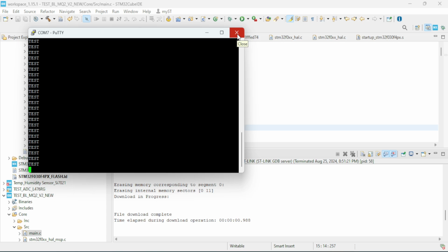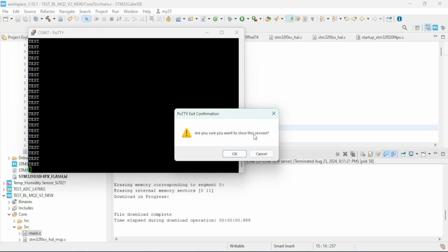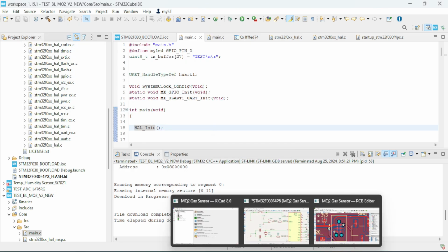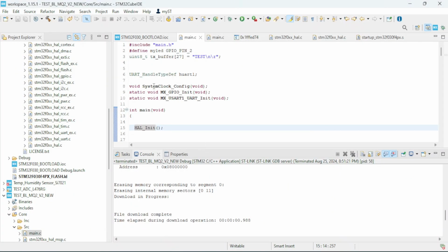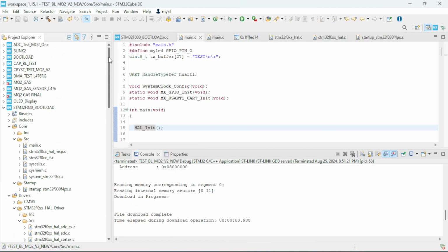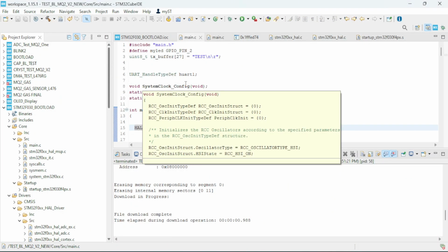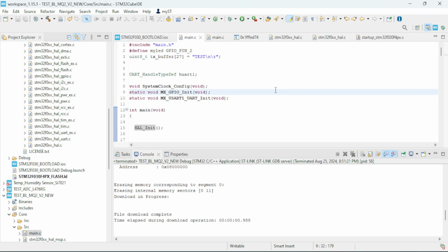However, I ran into a big problem, and it wasn't actually with the way that I made the code or the variables I was using or the inaccuracy of data. It's the microcontroller itself. The microcontroller that I chose for this only has 16 kilobytes of flash, and according to the IDE in which the code I created, it won't fit on the microcontroller. So even though the code that I wrote works with the Nucleo L476RG, it doesn't fit on this board. So unfortunately, I wasn't able to fully implement everything for this.